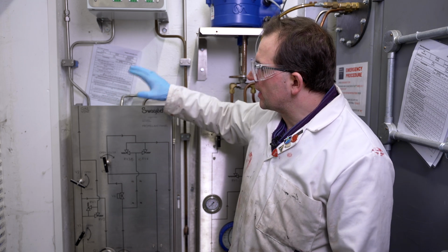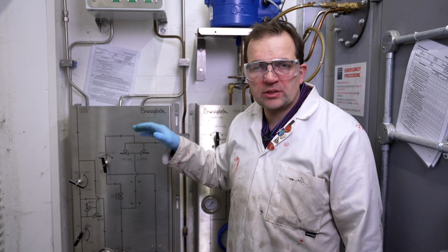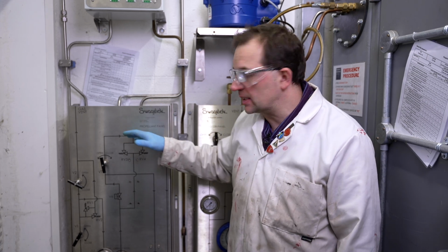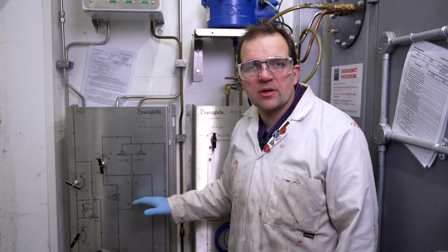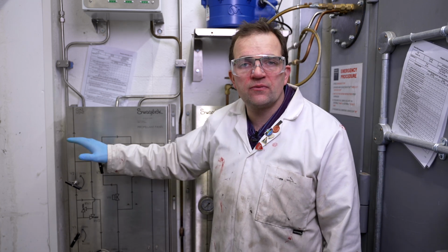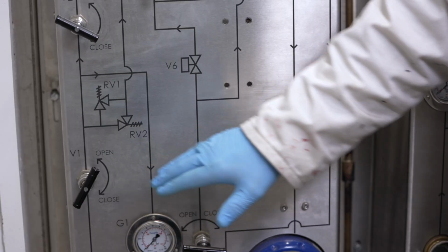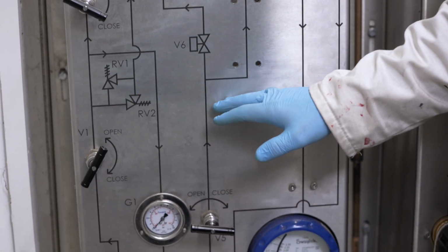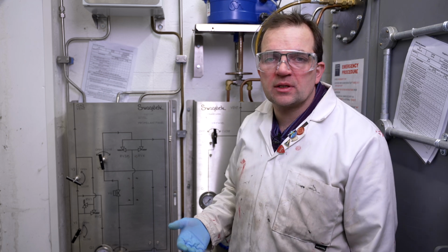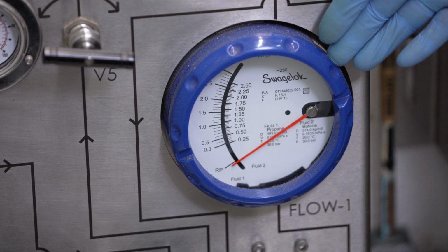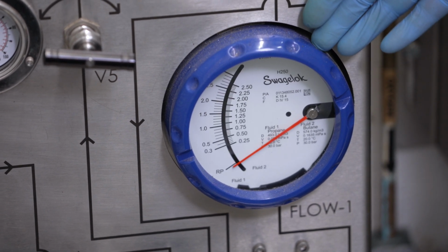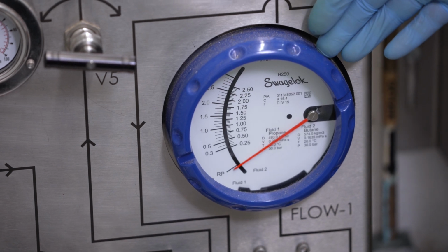As well as the regulations and being mounted in a position which works for your test facility, you need to think about the flow of the gases and the fluids going through the system. You need to be able to vent different parts of the system, and you need to protect your components from overpressurization. You might additionally want to think of putting some additional sensors in here. For instance, we have put a flow meter in line so we can measure the rate of flow of the gas or fluid going through the system. You might want to think about putting additional pressure sensors or temperature sensors in and around your system as well.